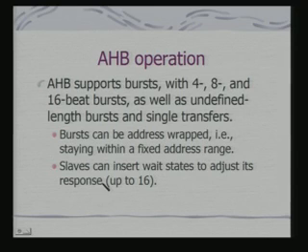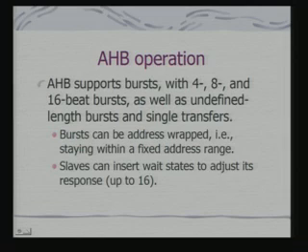In fact, if you remember, we said that if it is a sequential access, you can arbitrate and generate the address once, and the master can have the bus for transferring up to 16 words at one go. It can even be undefined length bursts, as well as simply single transfers.